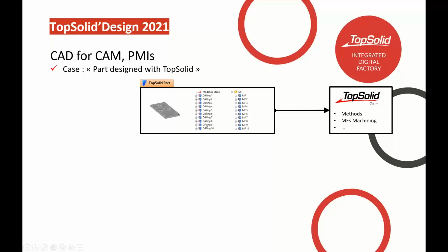So of course we have the natural drillings. Because we designed this plate, we can pass the manufacturing features to CAM. Okay, manufacturing features are a faster way to do drillings because the analysis is done in the CAD side already. And so CAM already knows what it is. But that's simple because, again, the design is done inside of TopSolid.